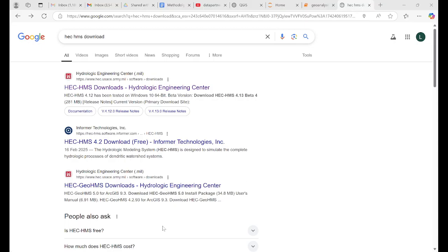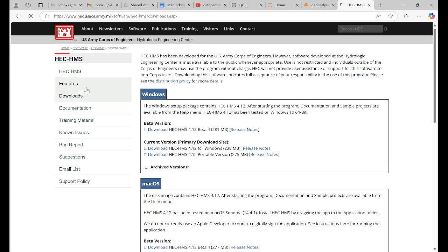So let's start. First we will download HEC-HMS. Just search for it on Google and this will come up. Since I'm using Windows, you can use the beta version, and download the HEC-HMS 4.12 portable version. I have already downloaded it; you just click here and download it.